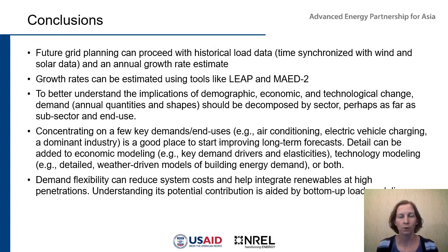I just want to wrap up now with a few key points. First, if you're not doing it already, then I would definitely recommend using hourly historical load data that's time synchronized with your wind and solar profiles to do your future grid planning. This is especially important if you are looking to integrate more wind and solar resources. It can be really important to see, relative to your load, when those resources are going to be abundant and when maybe they'll be lacking, and you'll need to bring other resources or strategies to bear.